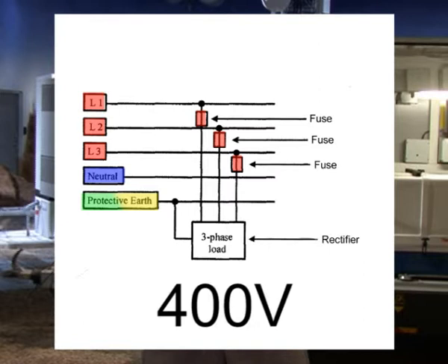This gives the best performance for the mains network with less risk for neutral overload, earth currents and so on. This way of connecting rectifiers gives an equal load to all three phases, which is the ideal situation. Note here that a three-phase connection needs three fuses or circuit breakers for operating safety. Normally, these three circuit breakers are connected in parallel with each other.